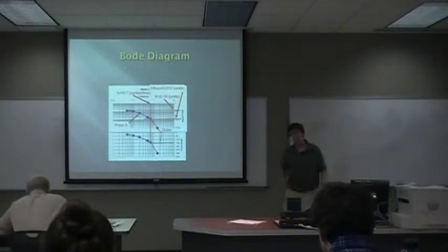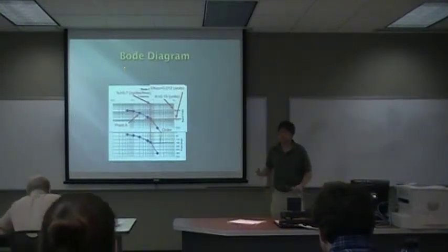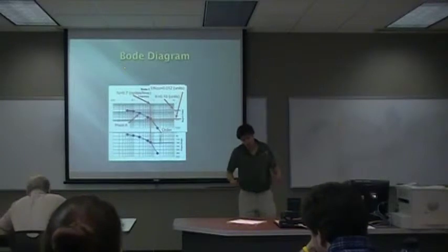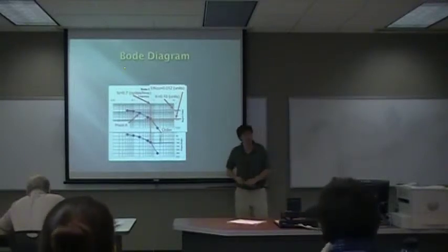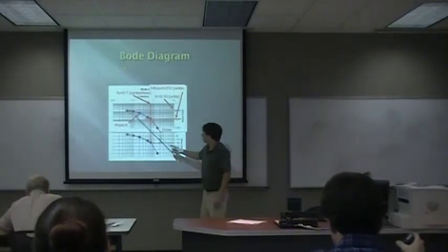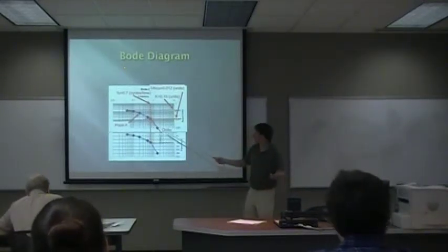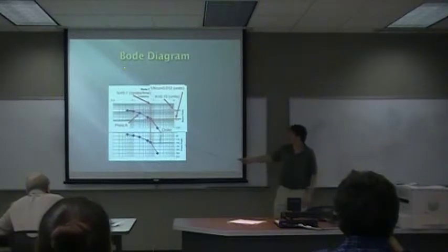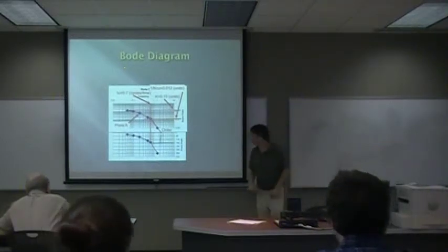And then each of these points can be plotted at a different frequency, starting at one set frequency and dropping down to lower and lower frequencies. It creates a nice plot of the amplitude ratio and phase angle for the system.